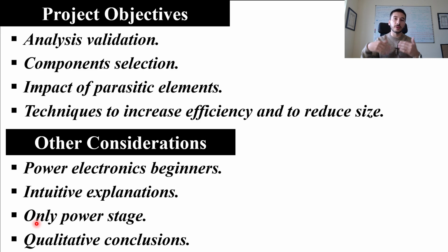For instance, if we increase the switching frequency, the conclusion that we are going to get is that switching losses rise, but the specific increase that we will see in simulation is not important, because the simulation models are not perfect. Okay, so in this way we will see a lot of trade-offs that we have to solve, or alleviate, as we progress in the design of a converter.